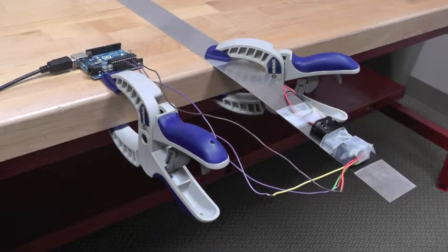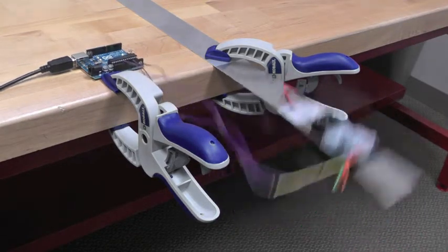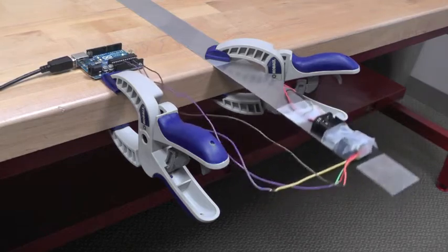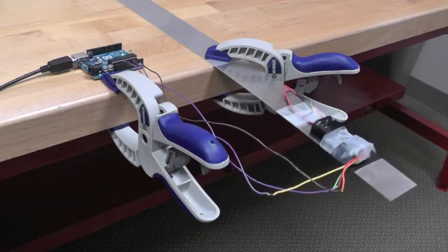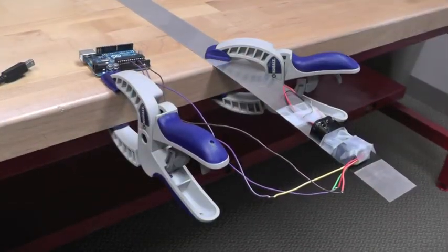To run the experiment, once the accelerometer is attached to the metal arm and the code has been uploaded to the Arduino, simply depress the metal arm and release. Once the metal arm stops oscillating, you can disconnect the Arduino to stop data recording.